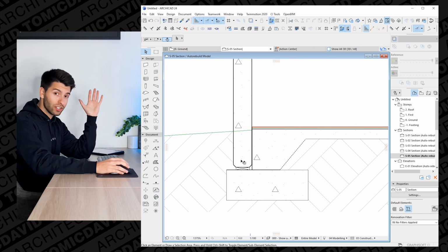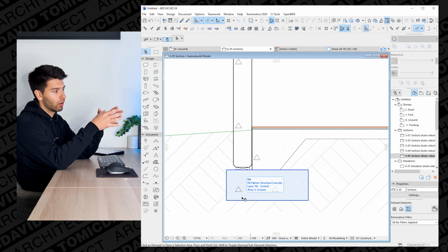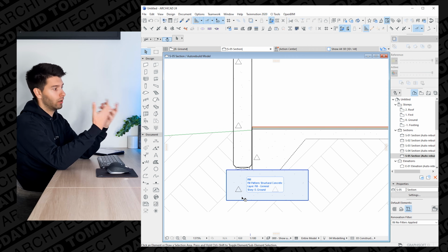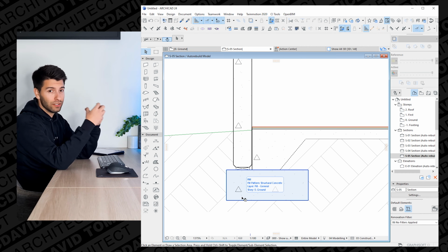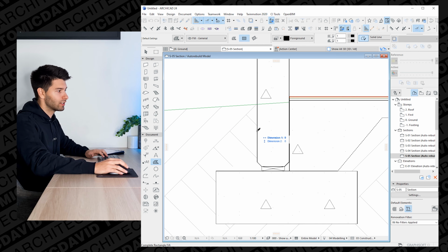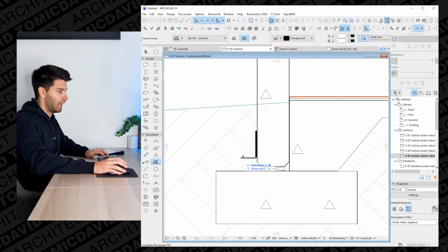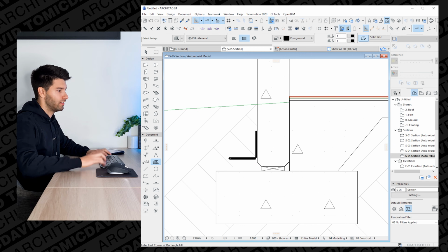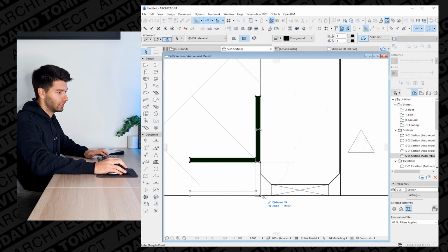Now obviously you can't just bring up a giant concrete wall and sit it like this against a concrete footing and pad some earth next to it and hope for the best. It actually has to be physically connected so it doesn't fall over whenever there's a light breeze. Now I'm just going to make a small little cleat here. Let's call it 10 mil by 150 and do the same thing here, 150 by 10 mil. We'll connect them and drag that to the bottom.